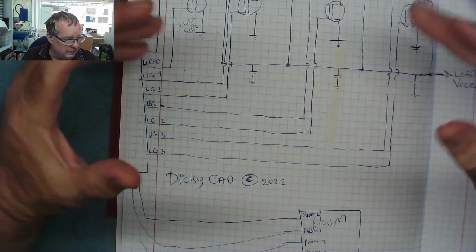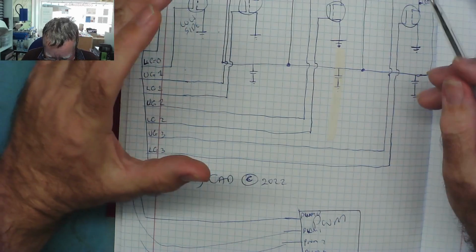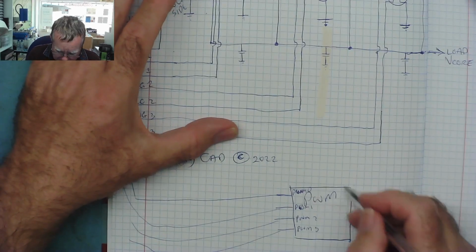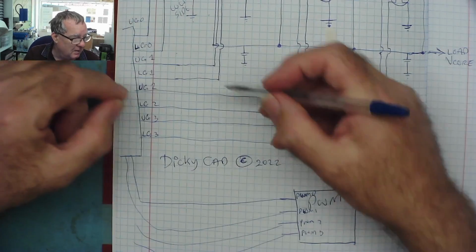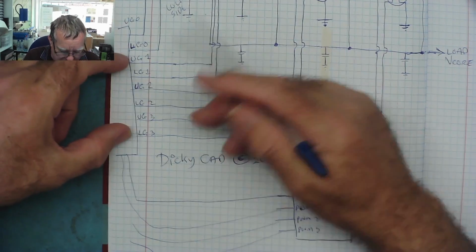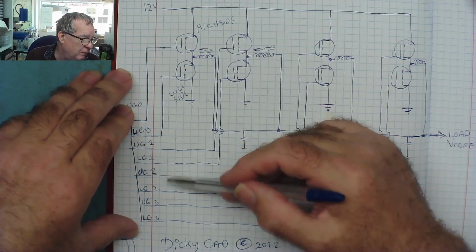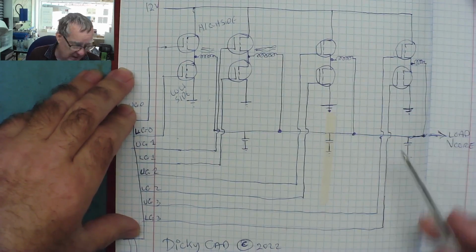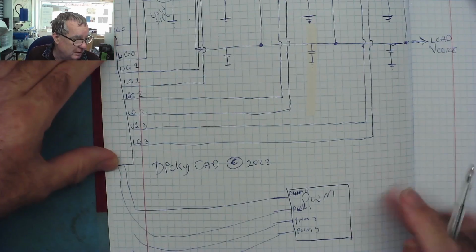So you'll often find motherboards and graphics cards where you have a pulse width modulator, then you have a driver chip, one driver chip for each pair of MOSFETs. So 4 driver chips, 8 MOSFETs, one pulse width modulator.